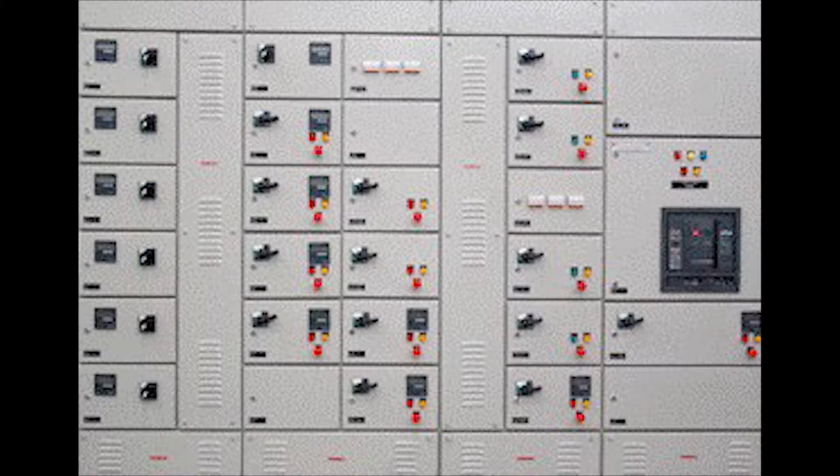In factories and industrial plants, process loads are the motors, heaters, compressors, and conveyors that form the main business of the plant. Process loads can normally be found on either mechanical equipment lists or process and instrumentation diagrams. Their power source originates from a motor control center. Voltages range from 480 to 4,160 volts.